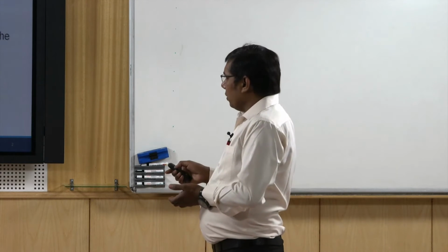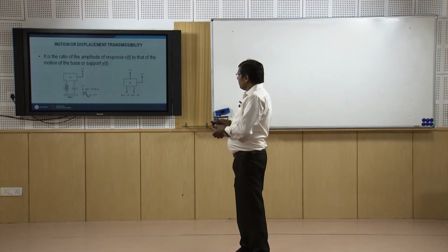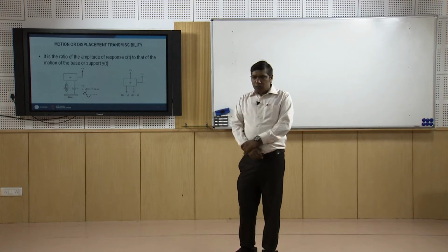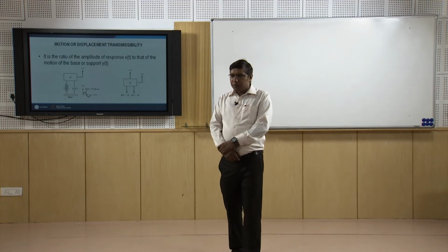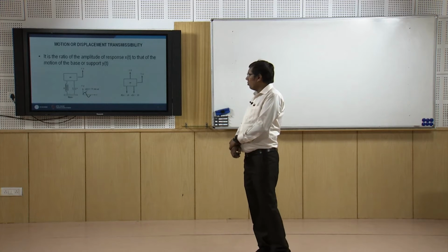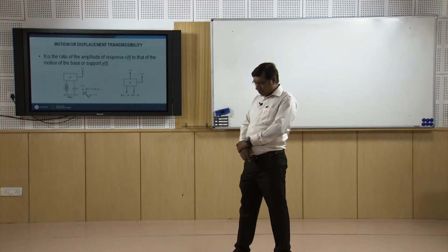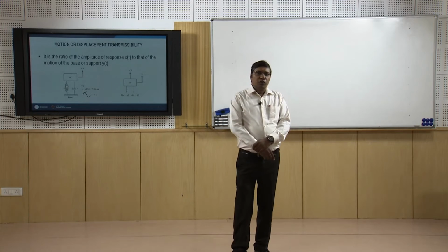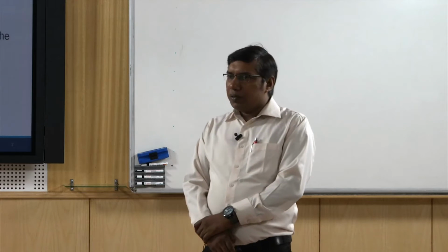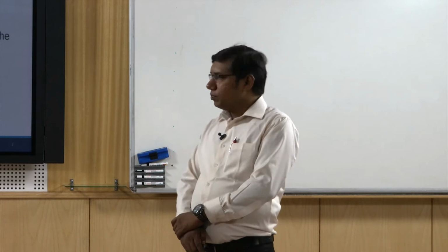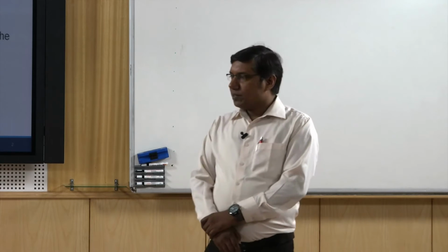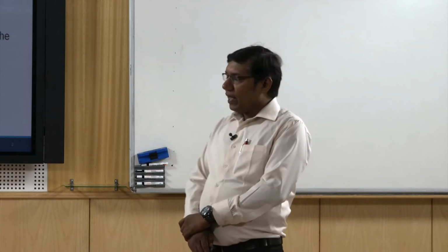So we can see that this motion transmissibility, we also call it displacement transmissibility. It is the ratio of the amplitude of the response x to that of the amplitude of the support.